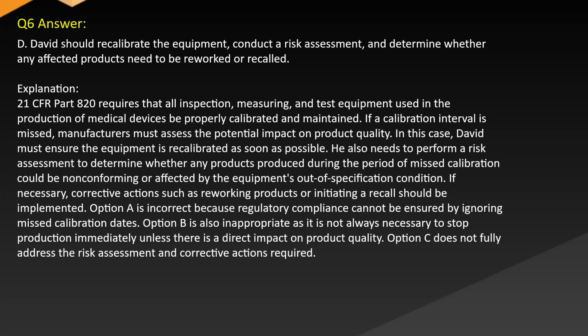He also needs to perform a risk assessment to determine whether any products produced during the period of missed calibration could be non-conforming or affected by the equipment's out-of-specification condition. If necessary, corrective actions such as reworking products or initiating a recall should be implemented.